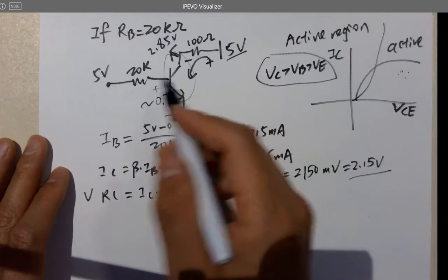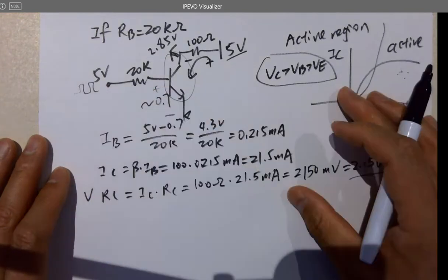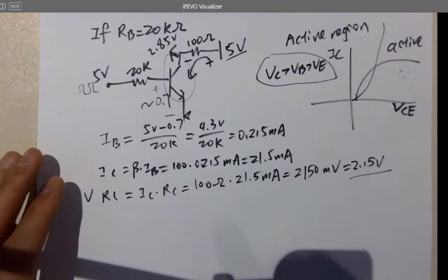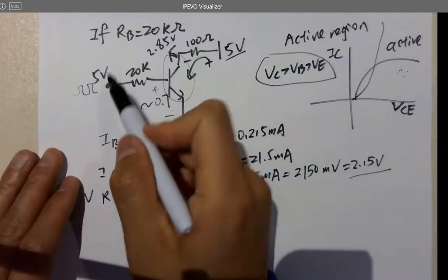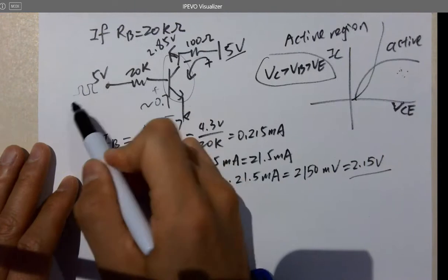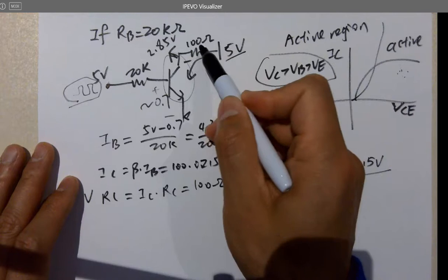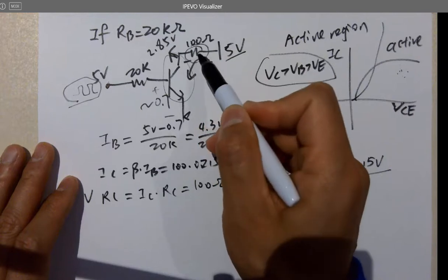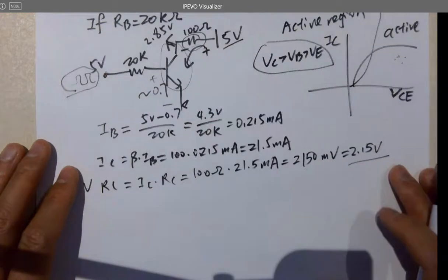The reason is you can turn the motor on and off using a low current, low power pulse from the Arduino GPIO, right? You can just program it, do a digital write, low, high, low, low, high like that. To turn this on, you use a low current pulse, and it's going to supply a little current to the load. That little thing is the load, the device it's going to drive, okay?